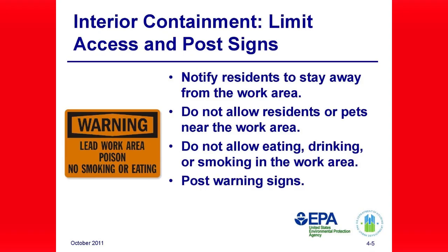Before the job starts, notify the residents not to enter the work area and to stay away from the vicinity of the entrance to the work area as much as possible. Residents and pets coming and going can easily track lead-contaminated dust into non-work areas throughout the home. Non-work areas will likely not be cleaned up promptly or properly.